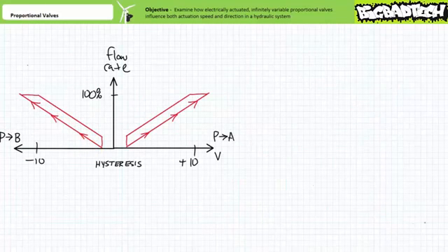Another proportional valve peculiarity is something known as hysteresis, where hysteresis is the spool's tendency to move a predictable amount for increasing voltage magnitude, however, exhibit different amounts of movement for decreasing voltage magnitude. I like to think of hysteresis as the magnetic equivalent to friction, observable as slight spool misalignment for equal applied voltages. An analogy might be placing your foot exactly in the center of a tread going up the stairs, but slightly off-center of the tread when you go down the stairs. You're still going up or down the stairs, but you're ever so slightly off position pending direction of movement.